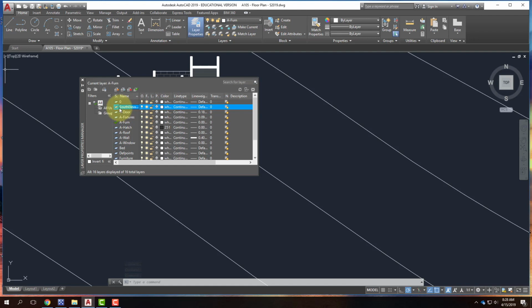And with the south elevation, I'm going to leave the line weights just at the default for right now. We'll come back and deal with the line weights a little bit later on. Line weights in elevations tend to be less layer-based and more just custom. You assign the line weights as we go.